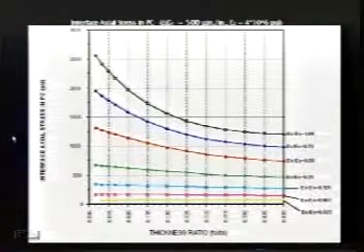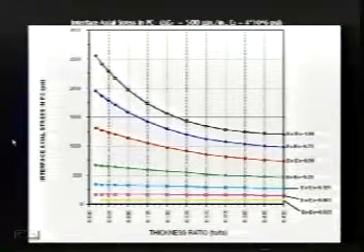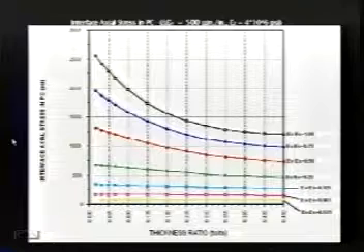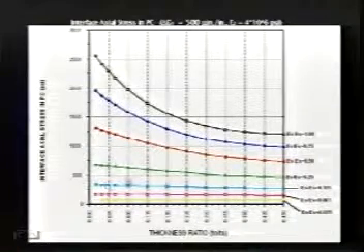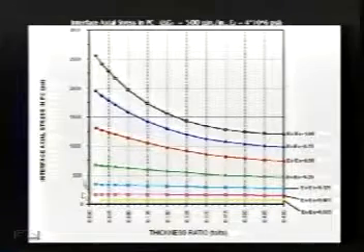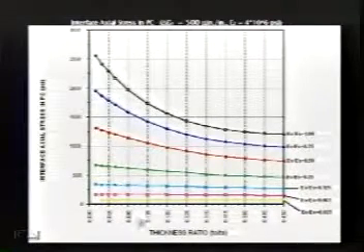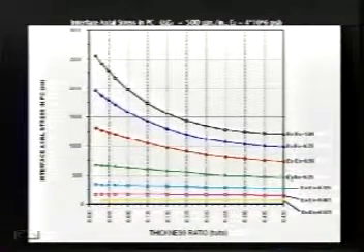Now normally when you do the calculations, you'll see later it never is quite 500, but you can always ratio it out. And so it's easy to use these curves and come up with the stresses that apply to your particular case. But notice on the bottom, this shows the thickness ratio. These values are the ratio of modulus of elasticity between the overlay and the concrete. And this will give us then a stress.